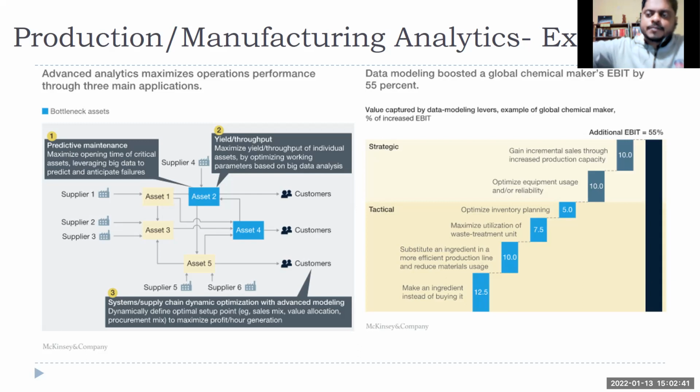You are predicting that this compressor is showing problems and it might stop by tomorrow. So before it shows the problem, your backup compressor will go in, and when the shift ends, we will put in the backup compressor, and the existing compressor will go into the maintenance shop. So rather than waiting for the problem to happen, you are predicting the maintenance schedule and managing accordingly.